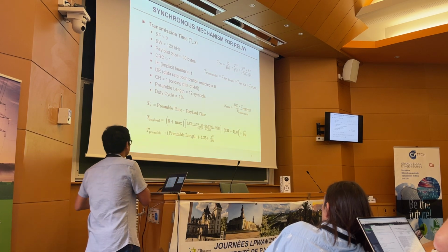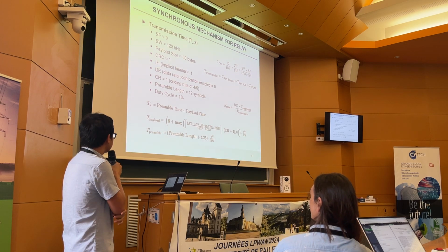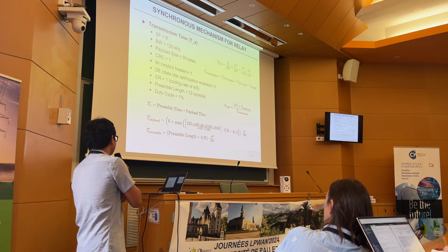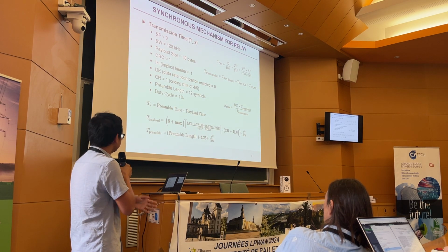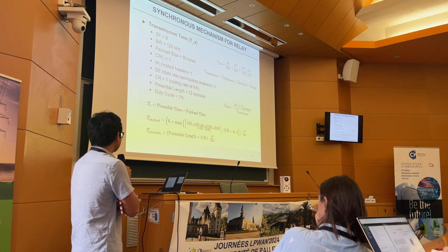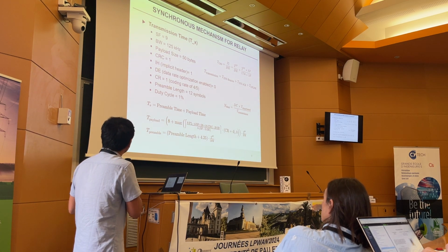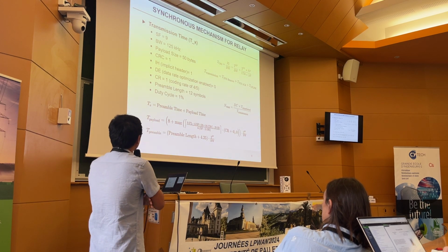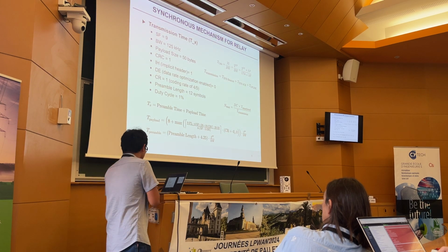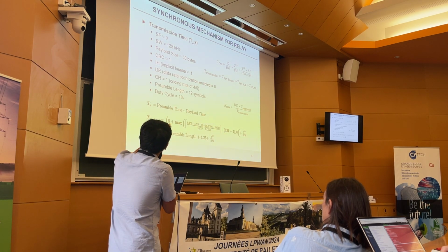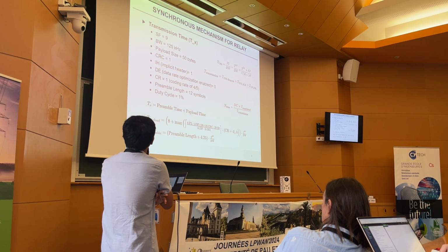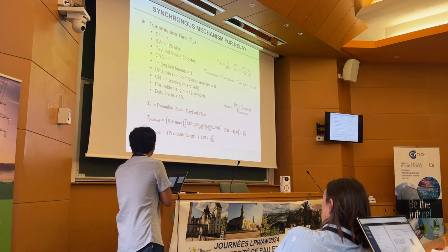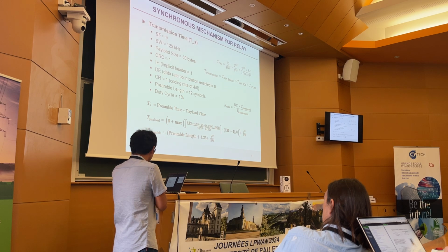So to evaluate the power consumption, to estimate the battery life, and to estimate the maximum number of end devices that can connect to the relay, we assume the transmission parameters like this: basically a 50 bytes payload, SF7, a duty cycle of 1%, and a preamble length of 12 symbols.